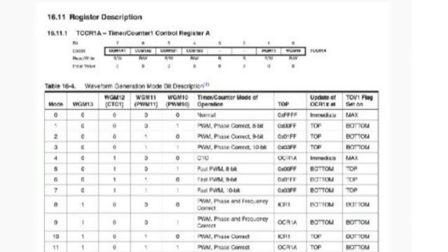I hope you can see this. At the top is the timer counter control register. And you can see that there's 8 slots there labeled 0 to 7. And they're all read and write. And they all have a bunch of kind of quasi-mnemonic names like WGM10, which is waveform generation mode 1 for counter 1, and it's the 0th bit. And then you look down at this table that's a couple pages down in the data sheet, and it tells you how setting all of these different bits sets it into different modes.